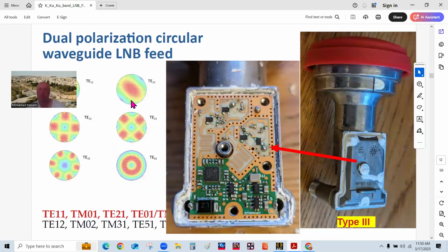This is the type where we have a solder bulb in here that goes in the middle of the waveguide and picks up the vertical. And of course, these are two active GaAs FET devices that pick up the signal with very little noise figure. In this case it's Ku band, so these have about 0.5 dB. Once it's implemented with all the input and output matching, you get about a half dB of noise figure. Then we go into this image rejection filter and onto the MMIC chip that converts the signal and routes it to the IF.